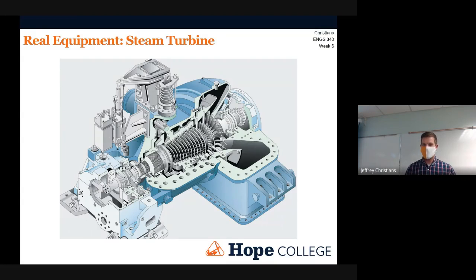So look back at your notes. The turbine part is the vertical line on the right-hand side. What's going into our steam turbine, as we have the TS diagram drawn, is a saturated vapor. So it's a vapor that's just about to condense. Then as it's going through the turbine, the arrow is going straight down, so what's coming out the other side is a vapor-liquid mixture, as we have it drawn. A vapor coming in, a vapor-liquid mixture coming out.